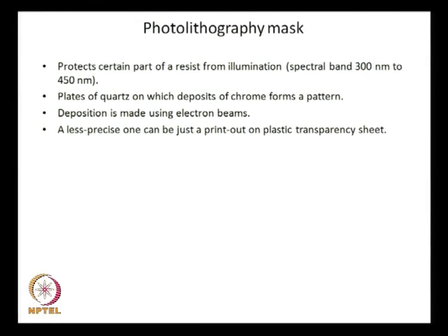So, we briefly point out, I will probably get into this photolithography process in the next class. What we briefly point out is that there has to be a mask, and there has to be a light source. So, light would be on the top, okay, and then there will be a mask. Mask means a certain portion is black and certain portion is white, okay, and below the mask there would be the wafer on which you want to create the channel, and you coat that wafer with a photoresist material, which is basically a polymer.